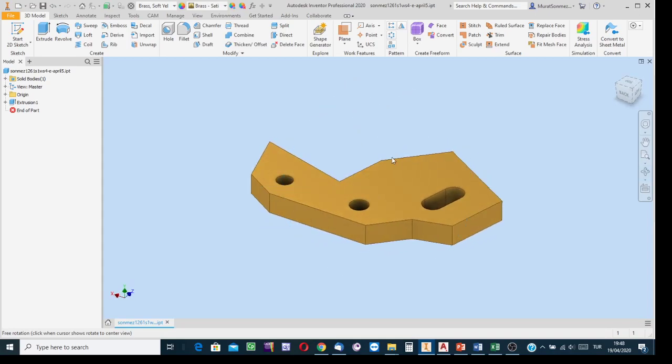Okay, you know, in 2D AutoCAD, mirror copy process requires mirroring line, but in Inventor 3D environment, mirror copy process requires mirroring plane. The things to do are the same. Not a matter software is AutoCAD or Inventor. Mirror copy.